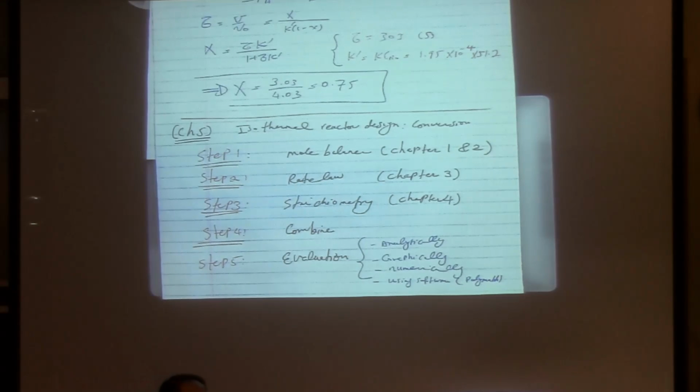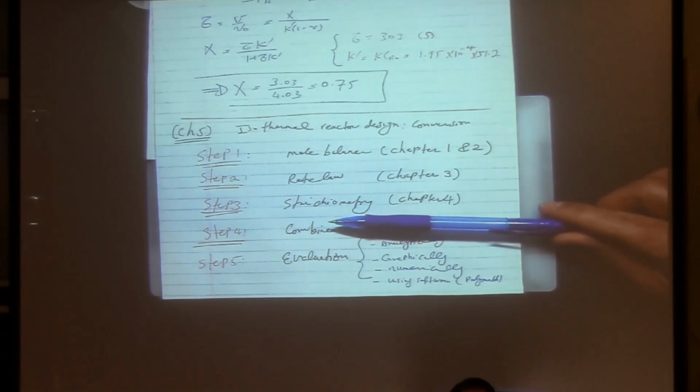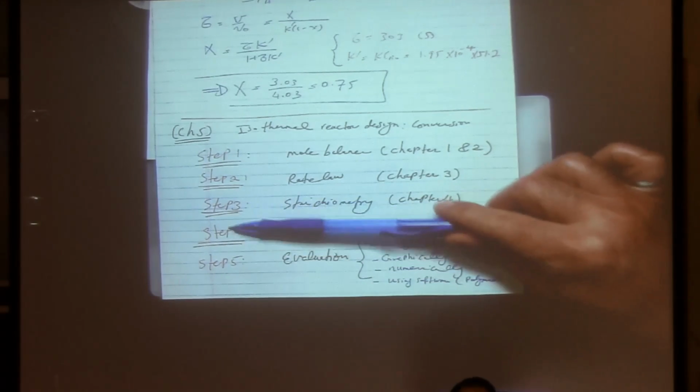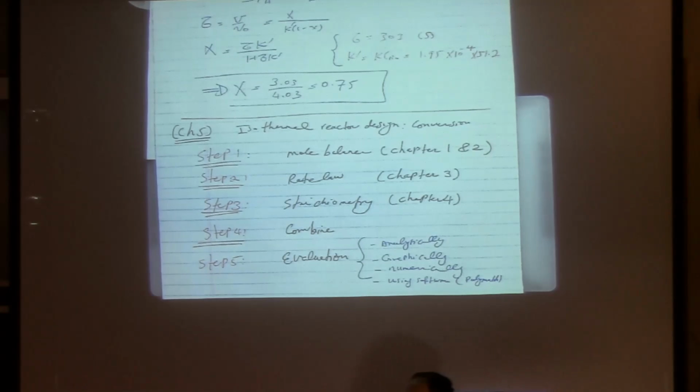So for that one, you introduce another step, between step 3 and 4, and that would be the energy balance. The energy balance of the reactor relates the concentration and K and other parameters to the temperature, and then shows how temperature influences these parameters, and then you have another equation added to this one. That's what it is for non-isothermal.